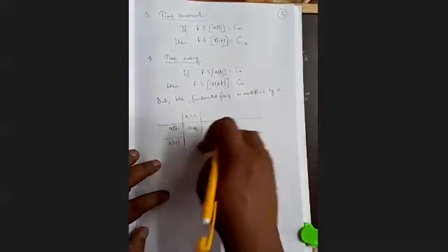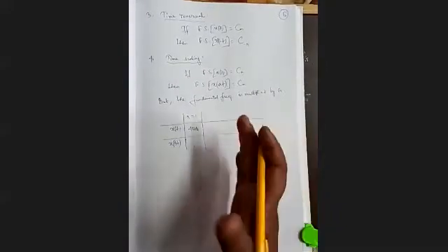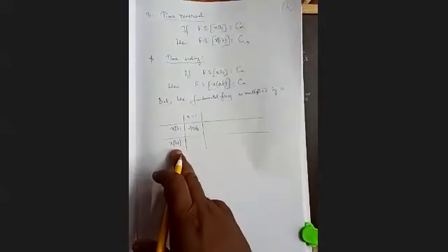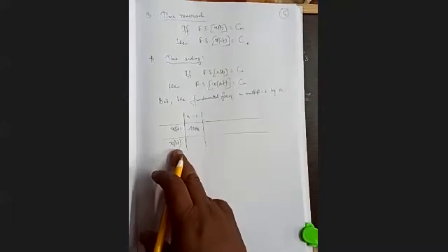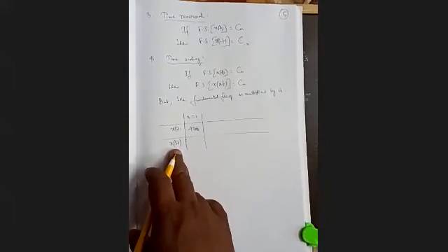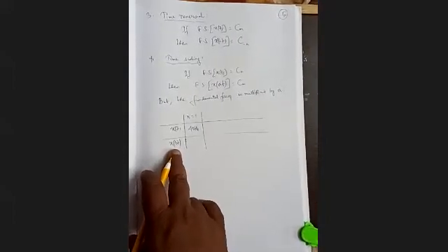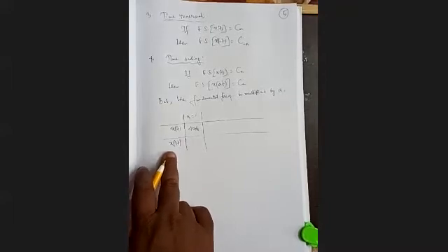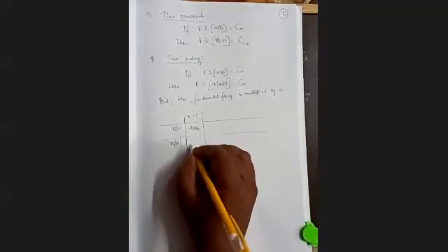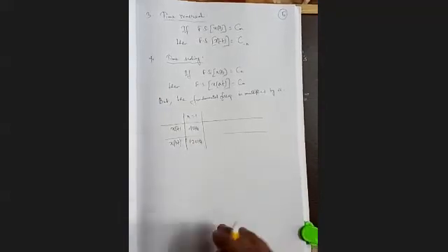For x(3t), what will be its fundamental frequency? The signal is compressed by a factor 3. So its time period will be shorter by the factor 3. Therefore, its frequency will be increased by the factor 3. So the fundamental frequency will be 120 Hertz.